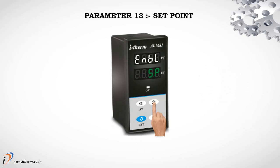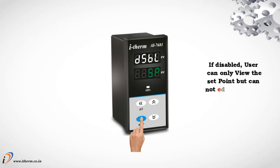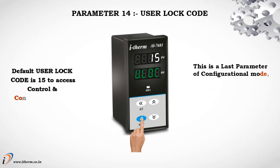Parameter 13, set point. If enabled, user can view and edit the set point in user list. If disabled, user can only view the set point but cannot edit it in user list. Parameter 14, user log code. Default user log code is 15 to access control and configuration list. This is the last parameter of configurational mode. Press set key to enter in run mode.